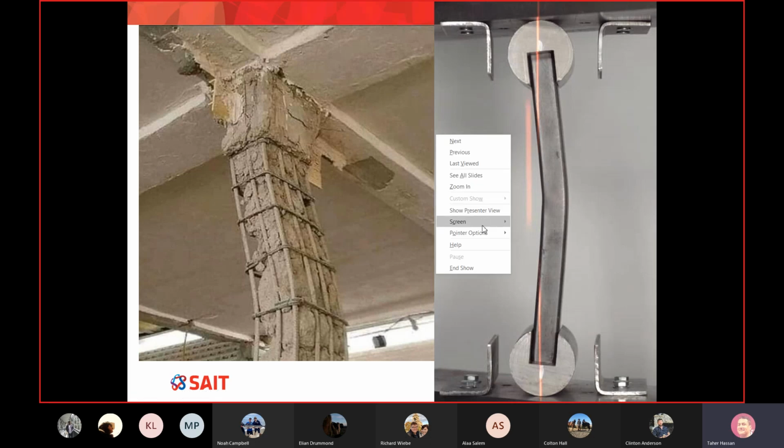So if we start here, remember, we are trying to apply compression. So my load was going here, applying compression. Well, after the buckling, there is a severe problem because my load is coming here, however my section has shifted this way. Whenever my section is here and I'm applying compression in the middle, I get a centric force, I get uniform stress on the cross section. I'm asking you, what if my section moves here? See what happens? Now there is a kind of eccentricity.